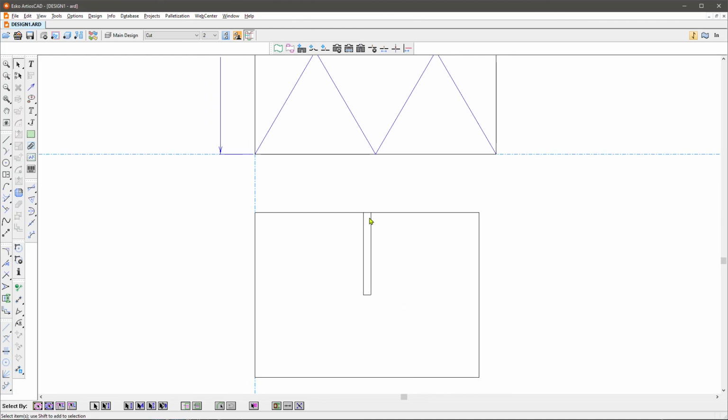Now, this area here, you've got to be careful with that, because if you use this trim tool, the trim interior section, to trim out the section here between these two lines, this particular design isn't necessarily complex enough to cause problems later, but a lot of the designs that you would want to rebuild, if you use that particular trim tool right there that just takes that out, it could cause issues with the math and force the design to blow up when you rebuild it.